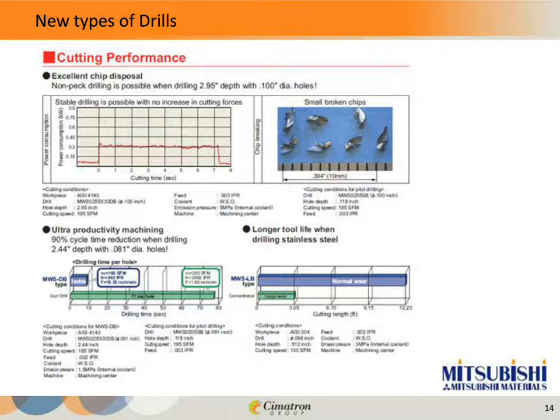Also here is the comparison of this type of drill versus a 1 flute gun drill. And you can see that with this carbide drill being 2 fluted, it's able to process the hole in about 8 seconds, whereas a gun drill processed the hole in 77 seconds. So it's quite a bit faster, and I wish that I had a third bar graph here to show how long that hole would take if we were using a high-speed steel drill with pecking, but I think you guys all have a good idea how much longer that would be.